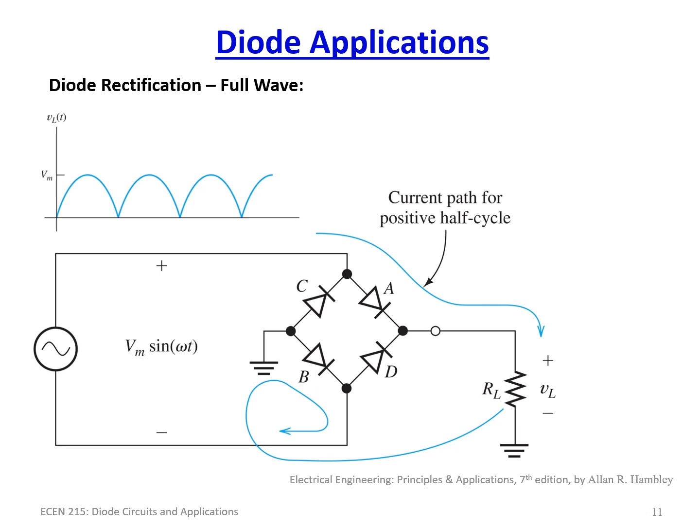Now, another rectification technique is known as full wave rectification, where you actually get the full wave. Instead of having this part here that's just completely ignored, it gets folded up and actually used. The way you do that is using this diode combination here, where you have current come through on the positive side, and it will flow through here, and will go through to the load, and then the load will return to the ground and then flow back this way.